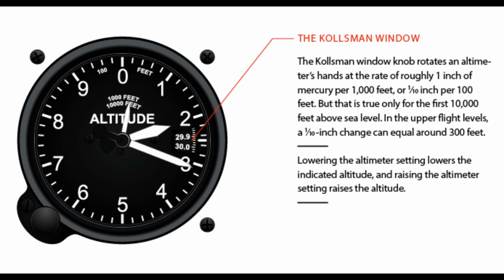For flights in the vicinity of airports, express the vertical position of aircraft in terms of QNH or QFE at or below the transition altitude and in terms of QNE at or above the transition level. While passing through the transition layer, express vertical position in terms of FLs when ascending and in terms of altitudes when descending. When an aircraft that receives a clearance as number 1 to land completes its approach using QFE, express the vertical position of the aircraft in terms of height above the airport elevation during that portion of its flight for which you may use QFE.